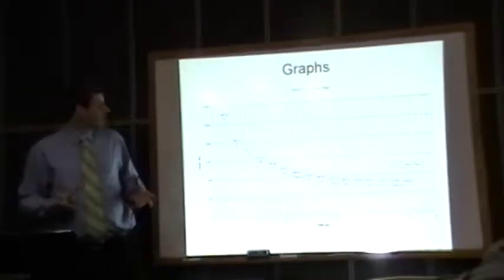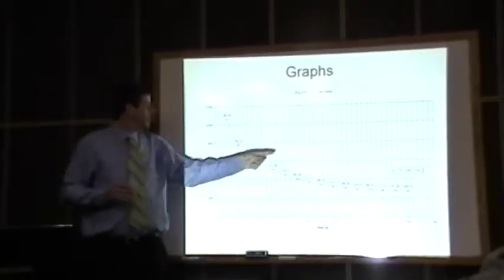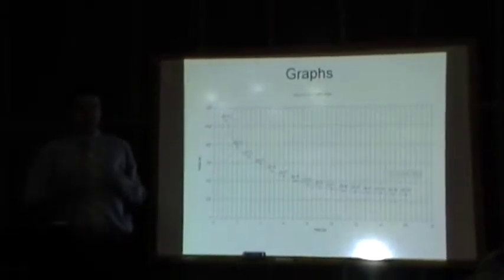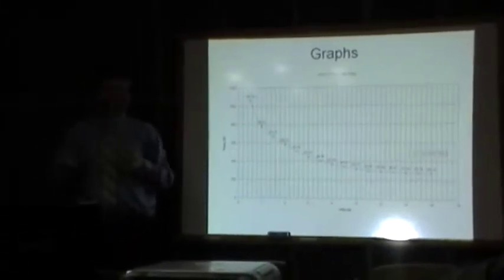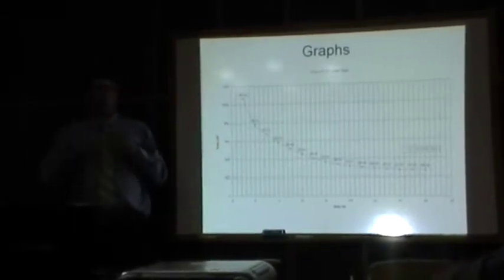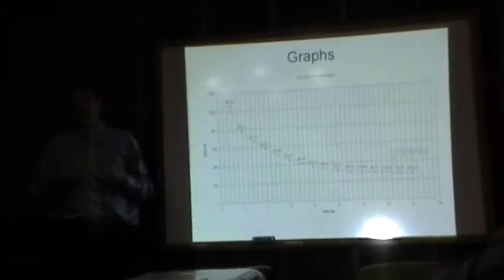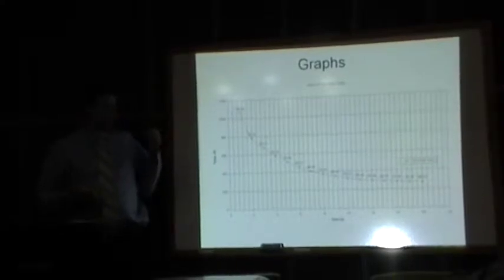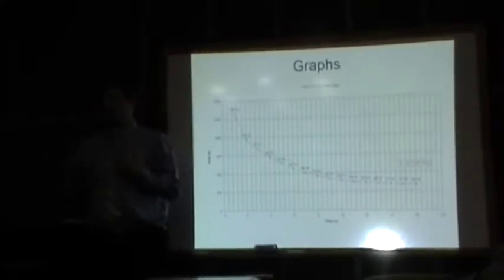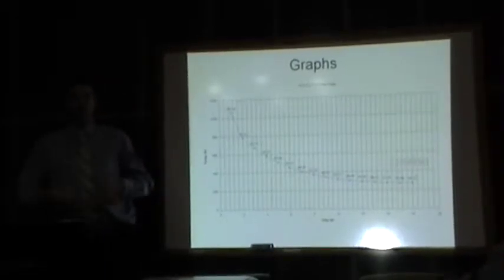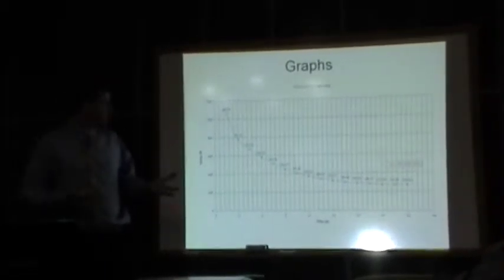This is the outlet temperature of the carbon dioxide. This was important to graph because the rocket equation for rocket thrust tells us that the velocity of the gas leaving a rocket engine is proportional to its temperature. The higher the exit velocity, the more thrust you have, therefore the higher the temperature, the higher the velocity, the higher the thrust.